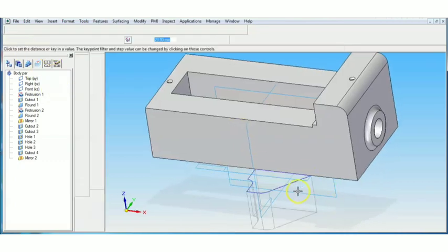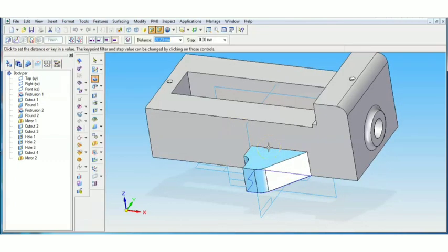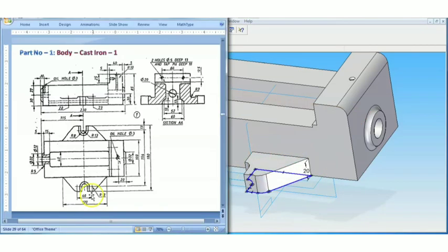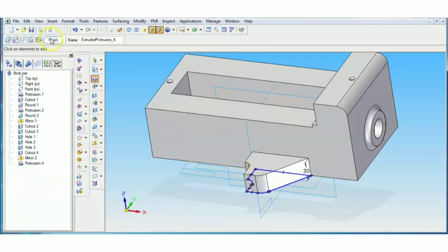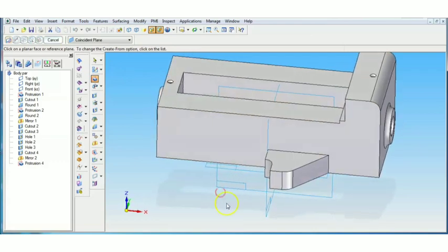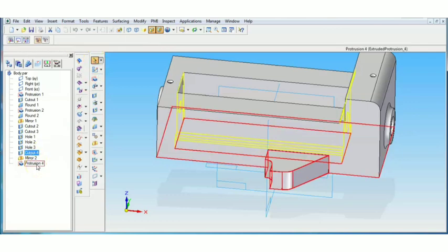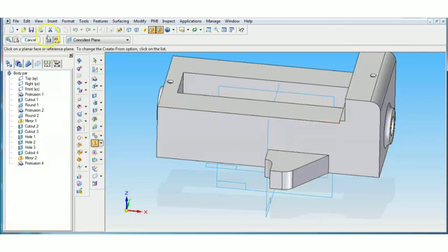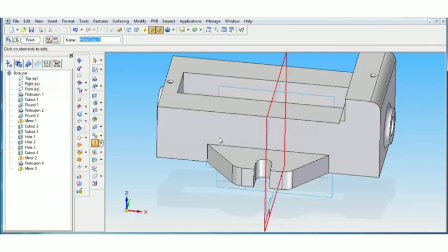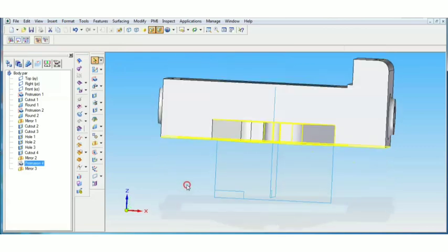So retain and extend it to 20 mm. 20 mm is given here. 20 mm is the thickness of that wing. Above that there is a double U, that you can create there. So finish this. Now you have to mirror this part. So select this protrusion, go to mirror using the smart command. Click here, you have got this mirror.